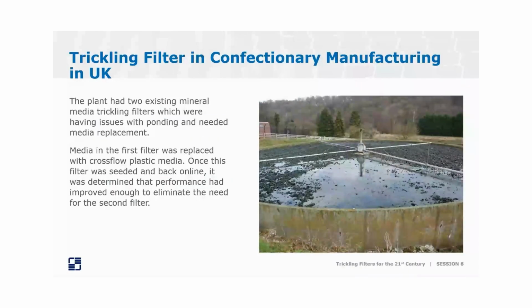Here's a system that was for a confectionery manufacturer. The plant had two existing mineral media trickling filters, which were having issues with ponding, as you can see from the picture, and needed media replacement.